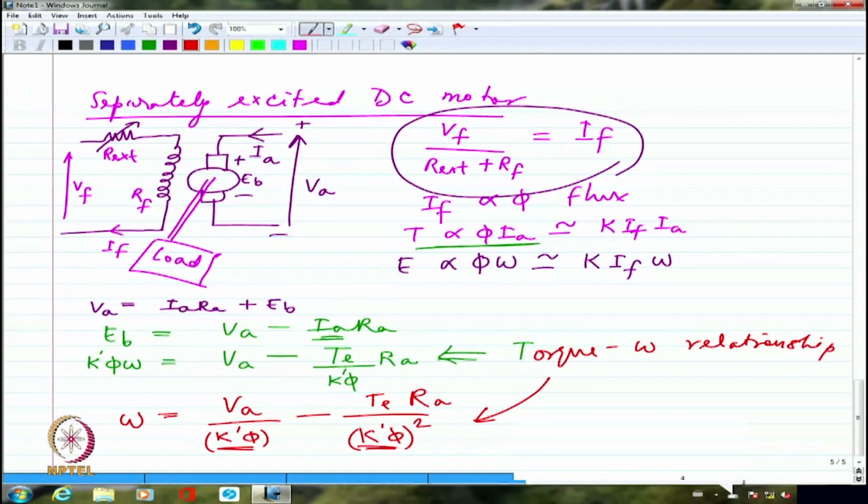I am just giving you an example. Let us say a DC motor is driving our elevator. Maybe 5 of us have gotten in, which means the torque to be developed by the machine is fairly a constant. So I can try to run the machine at whatever speed I want, provided I adjust my armature resistance, or externally I can include a resistance in the armature circuit.